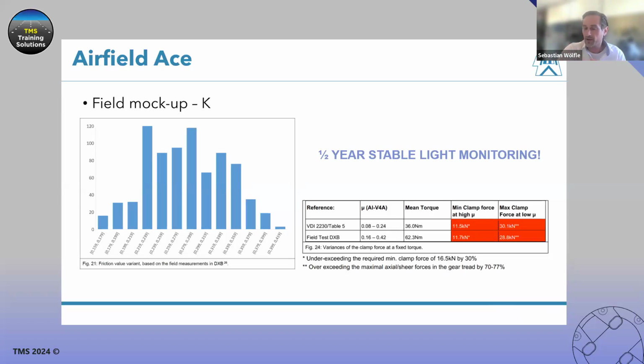At that airport, they used the OEM supplied screws A270, which have a maximum recommended clamp force of 17 kilonewton. So imagine 28 kilonewton would deform and break the screw itself. So we have a very tight situation with the materials supplied here.